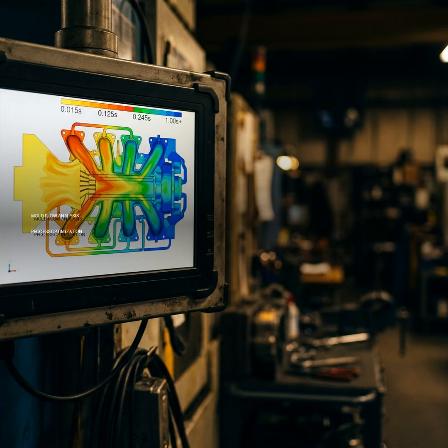Exactly. Then you move to packing settings. The purpose of packing is to compensate for any melt that hasn't completely filled the cavity, and crucially, to account for shrinkage after filling. We're talking segmented curves of packing pressure and packing time here. And cooling? That's got to be a big one for cycle time, right? Huge. Cooling time mainly depends on part thickness, but also melt temperature, mold temperature, and the thermal conductivity of the mold steel. We often use empirical formulas to estimate this, and you've got to set the cooling liquid parameters, ensuring enough flow rate to remove heat and maintain a uniform mold surface temperature for good part appearance.